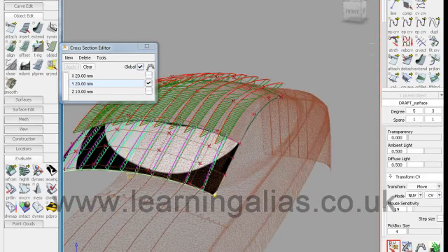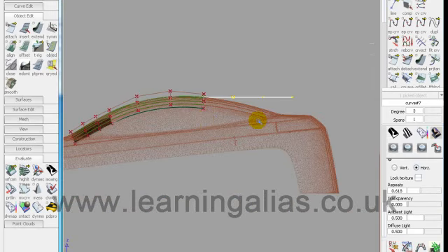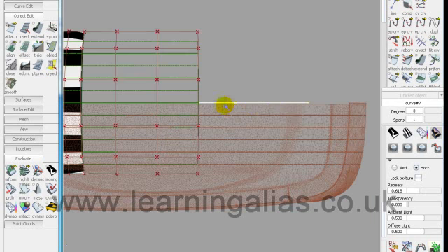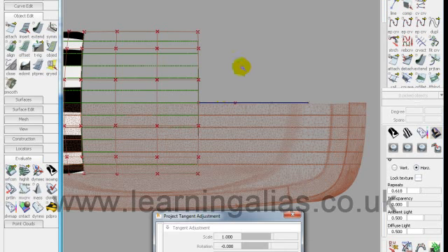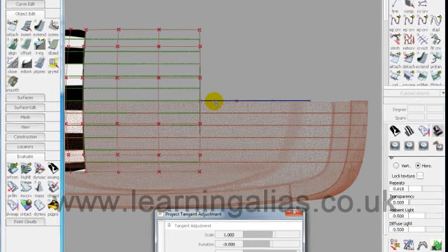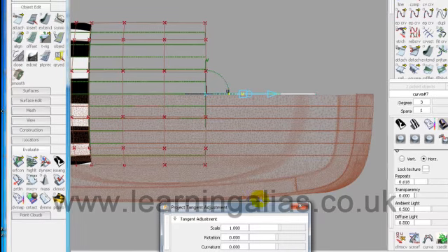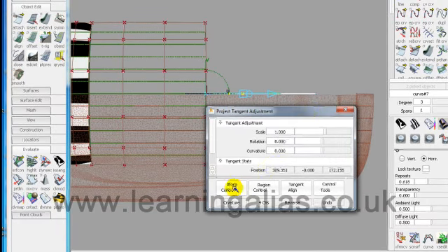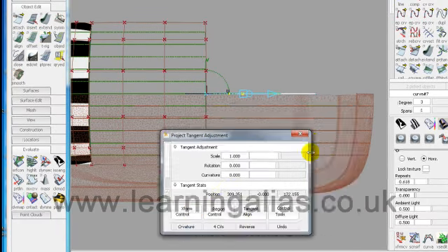So we do the rear screen. I'm not going to show you everything about the rear screen because a lot of it's repetitive, but what I will show you is the method. Put a degree 3 curve there on the center of this surface, and then use a project tangent tool and make sure it's set to curvature.